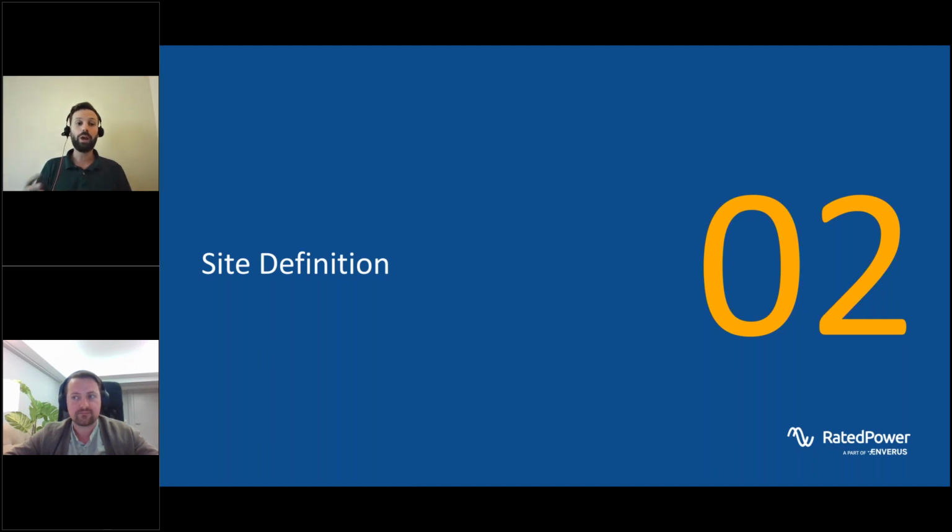We have 2 ways to define this layer. The first one is to define it inside PV Design in a specific section that we call Interactive Site Creator. The second option is to upload a KMZ or KML file with all these shapes inside. Regardless of the option you choose, these rules will always be the same.